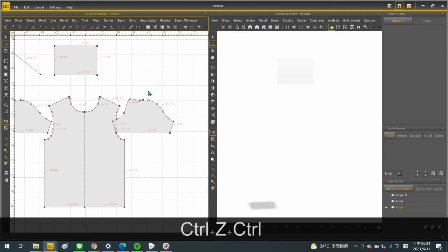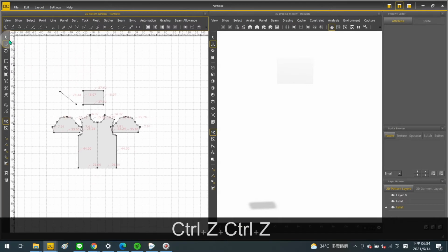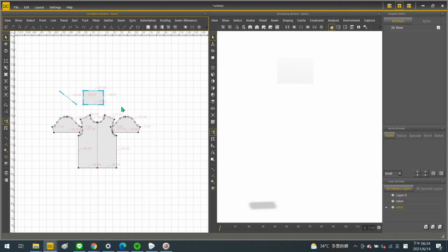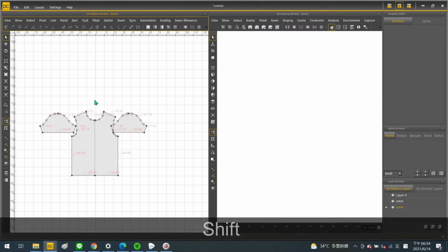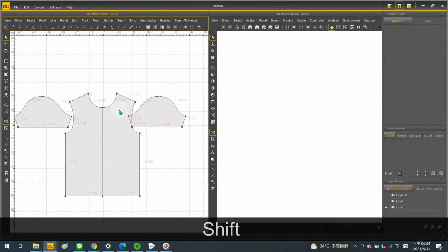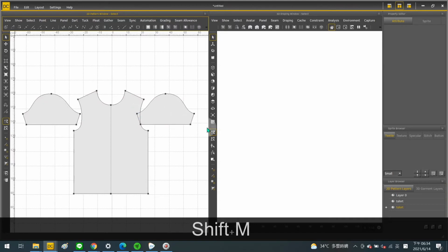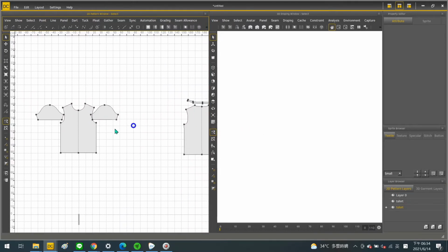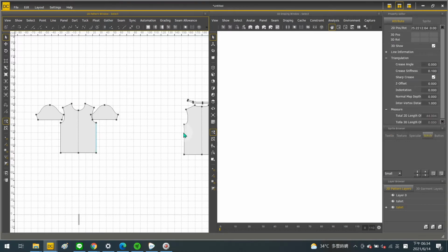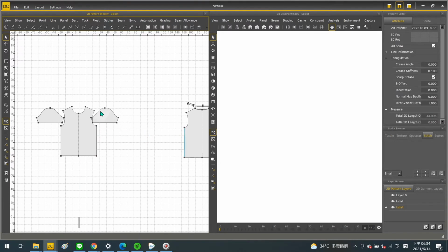Now let's get back to the pattern we just imported. Usually the first step is to clean the pattern, because in DC Suite, the contours of the pattern should be stitched together one by one. Therefore, the line arrangement should be the same as how it will be stitched. This will be explained in how to set up a pattern in the next video.